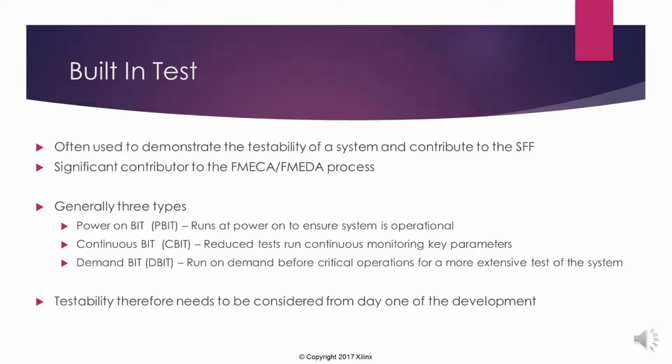Now this is where the new FPGAs and SoCs like the UltraScale and the Zynq come into play, because they have inbuilt XADC system monitors that allow the junction temperature and the device supply voltages to be measured and logged, and we can set alarms such that we can take action if they go too high or too low, so we can do a little bit of prognostics in there as well. And we can also pull through up to 16 external inputs, so we can have a very complex, very powerful built-in test and monitoring system with a very low overhead on the design.